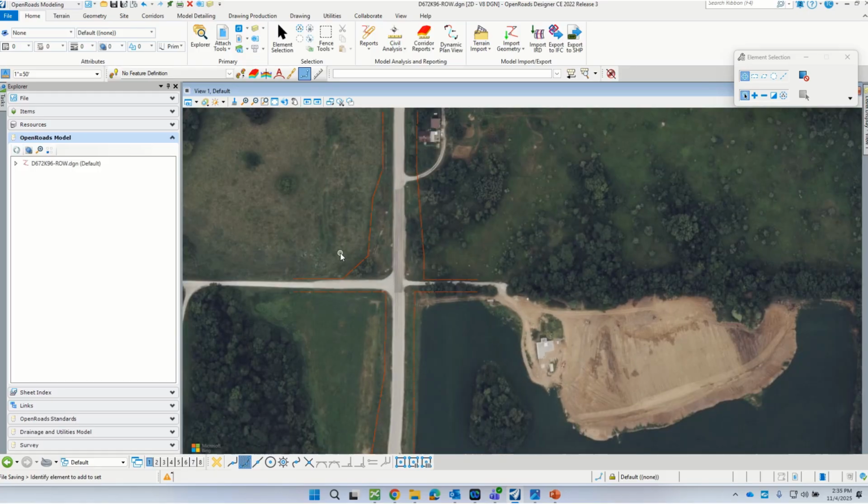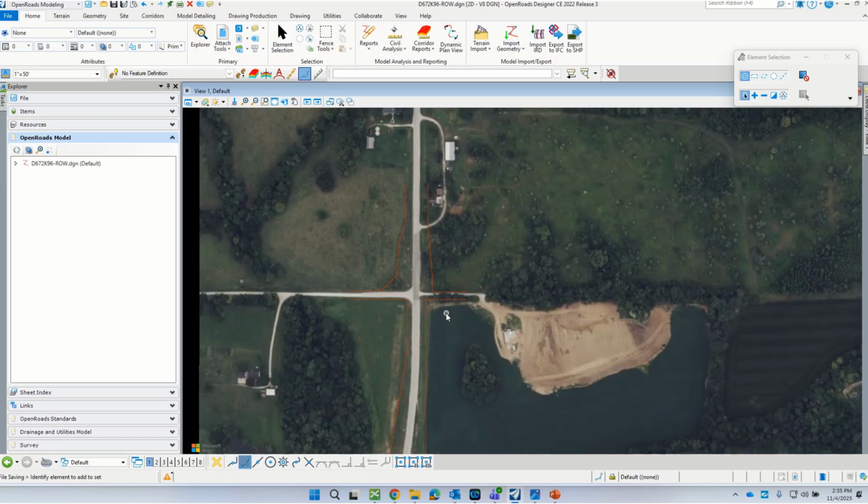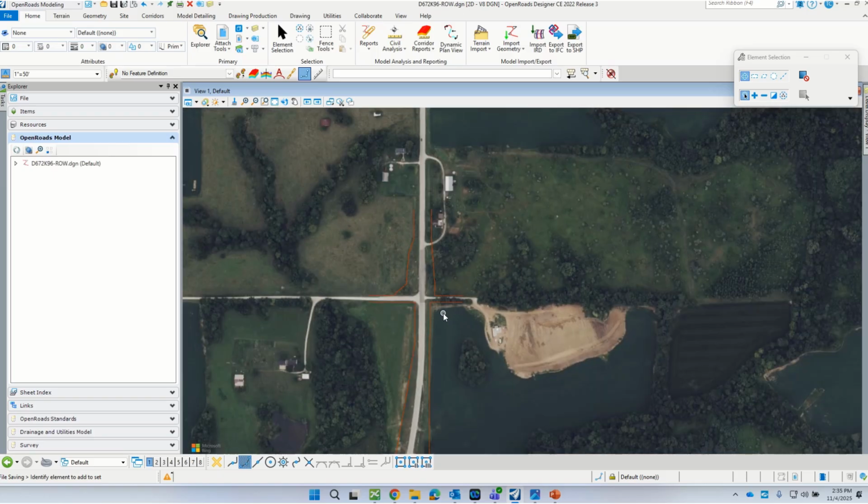And if it looks like you are going to be purchasing right-of-way, or you're going to be really close to it, then at that time there may need to be a land survey, actually. But usually initially when you're first getting started on a project, some of these right-of-way lines are just drawn by station offset, which is fine for most cases.